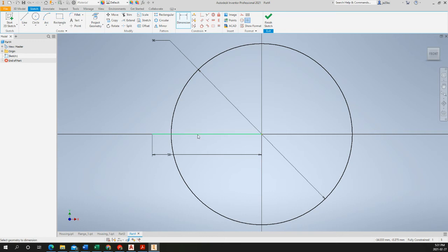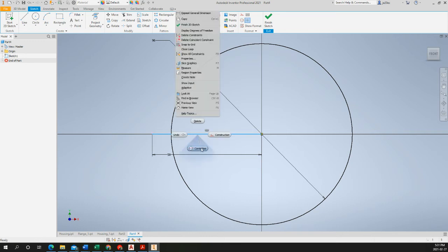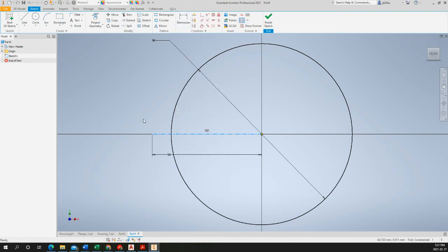Okay, and before I forget, select this line and I'll make it a center line. So I know it's just a piece of reference geometry. Now for my little bolt hole flange, I'm going to do one of these, and the center through hole is 10 millimeters in diameter. So we'll draw that. Body is a radius of 12, so that will be 24 millimeter diameter.